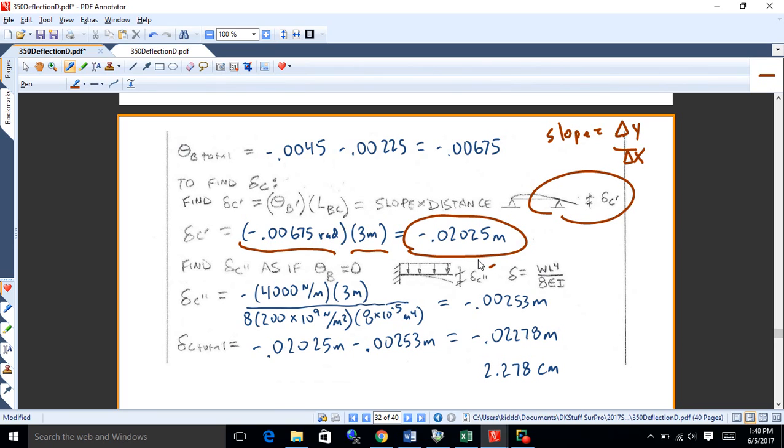So that's going to be from the formula for a cantilever now, because that's the best way we can model this. It's solid material running across B, so it acts like a cantilever. If you've ever seen a house with a little porch outside the bedroom, usually they just take those floor joists and just push them out, like on a second-story porch. That's what we're talking about here, and that acts like a cantilever. You just assume that that beam itself provides enough of a support to act like a cantilever.